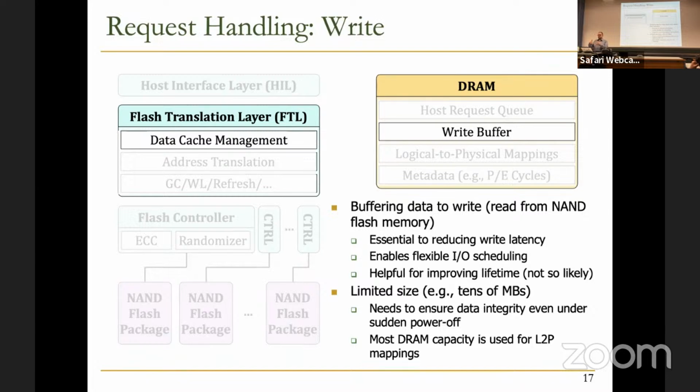So when you have your flash memory in TLC mode, which means you can store 3 bits per cell, it's quite slow. But then you can consider that you have a small flash memory, like some buffer, built from flash memory, but only used in SLC mode. Then that flash memory in SLC mode can be used as a write buffer or cache of your TLC or QLC flash memory. So people are trying to increase the size of this write buffer by doing some tricks, basically. Okay.